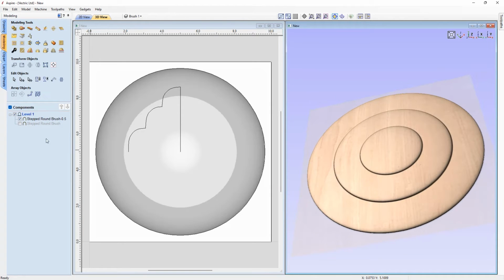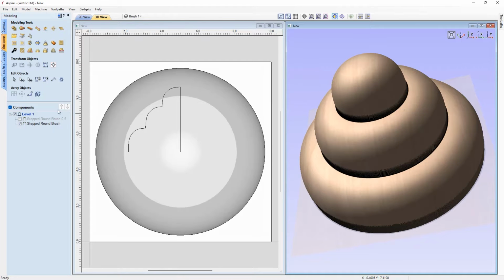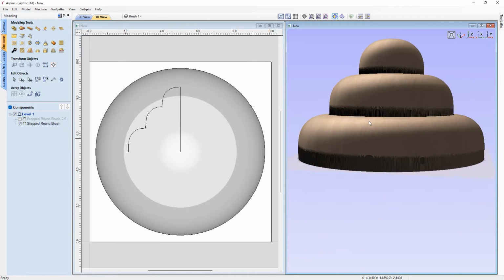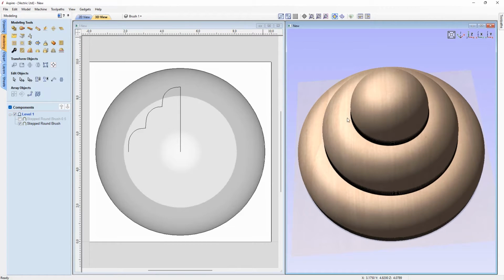We've got one that's really shallow and another one that has a height of 5.8737. It's got the full height in there. And when we create a custom brush, the aspect ratio of the brush remains the same as you create it. So if you use a low Z height component, it will not appear very strong when sculpting. The strength of the brush really depends on the actual depth of the brush that we make, which is why we've got two examples here, one that's fairly flat and one that's full of height. We're just going to look at how the two relate when we come to sculpt with them.